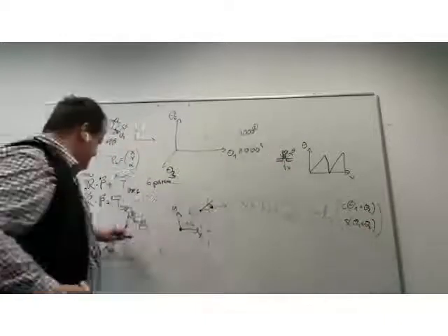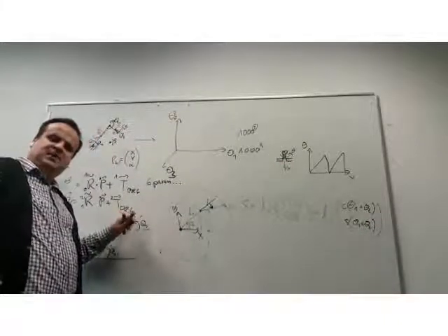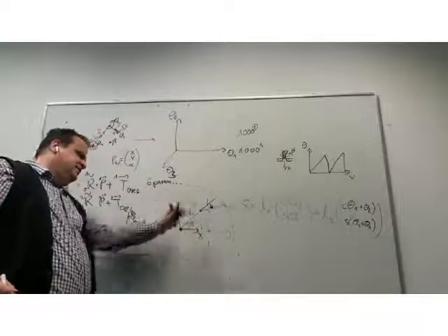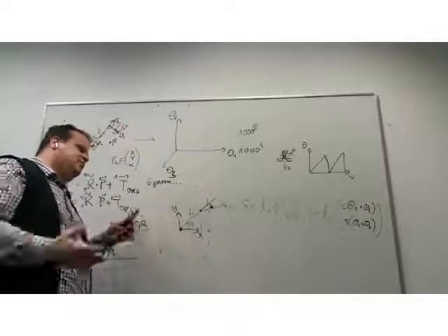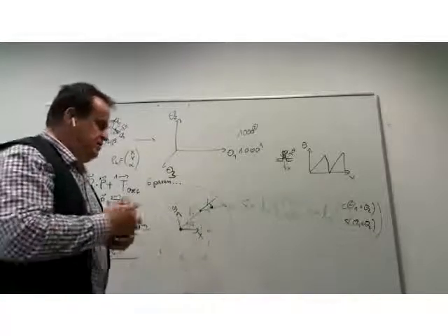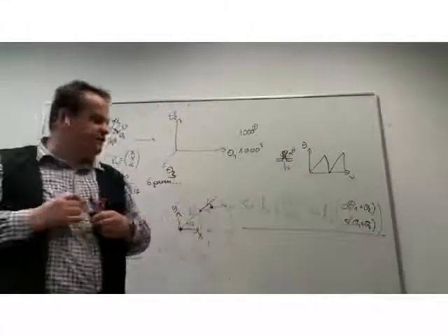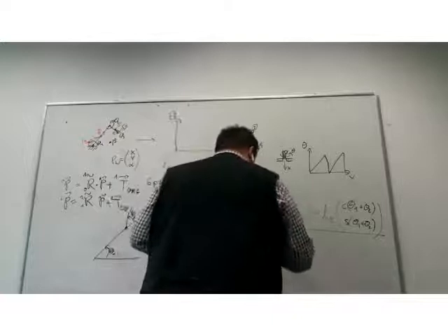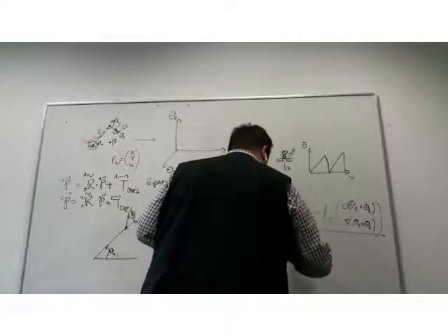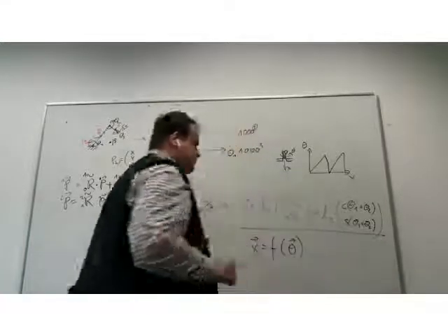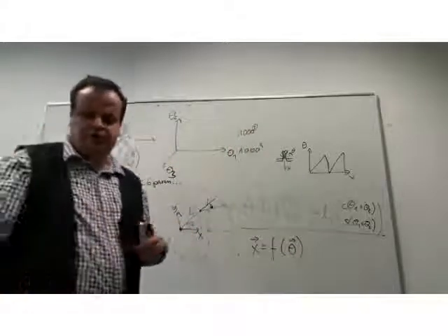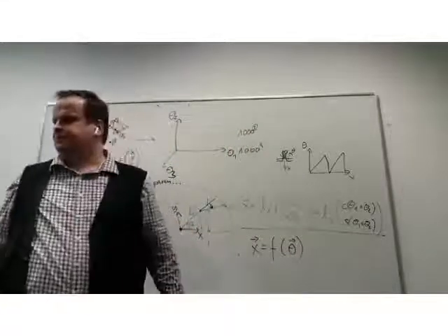It is actually the same thing as in the origin. I'm having now just an orientation of the second joint as a result of 2 orientation changes. And you see, this would be an example of my forward kinematic function, calculating x as a function of the 2 angles theta, knowing the geometry in the system.